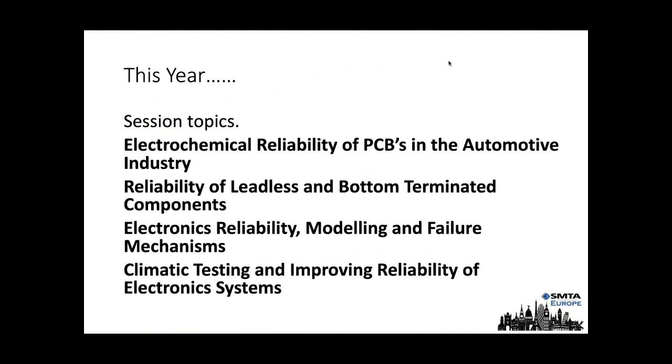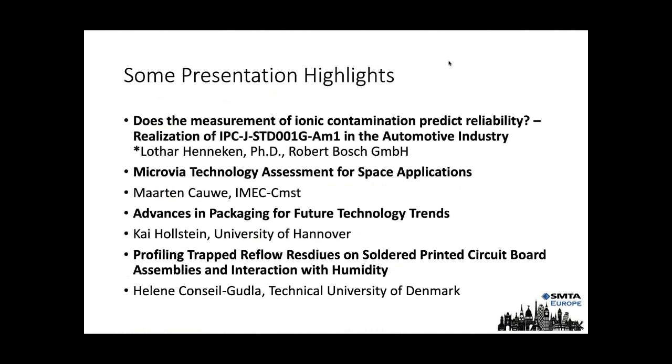And then the other one, of course, involved in high reliability and harsh environment stuff. There's always a huge amount of testing. A lot of this is done now in climatic chambers. The HAST tests and all the others are becoming harsher and harsher, and it's always a continuous goal of all the people in the industry to improve the reliability of these systems.